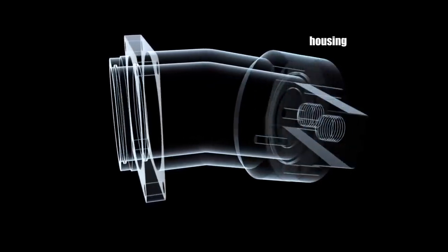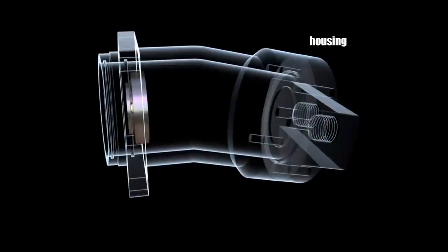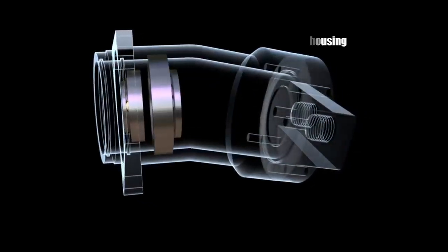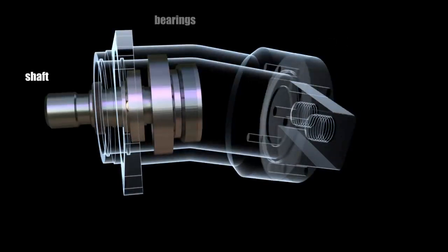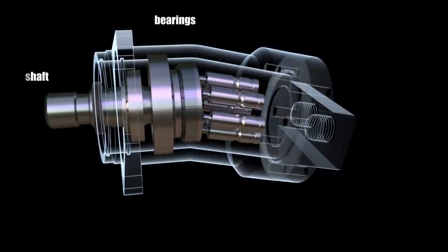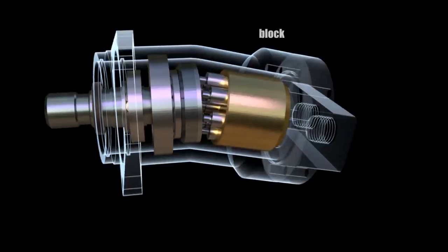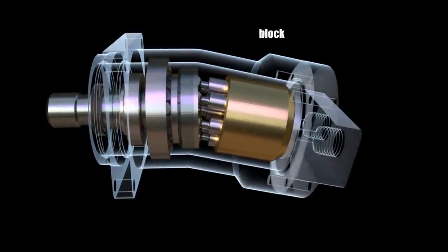The pump housing has a distinctive curved shape, and its shaft is supported by bearings. The pistons are attached to the shaft with spherical bearings and placed into the inclined block mounted on the axis. In the pump shown, pistons are used to transmit the rotation from the drive shaft to the axis, while some other devices use cardan shafts as a drive unit.